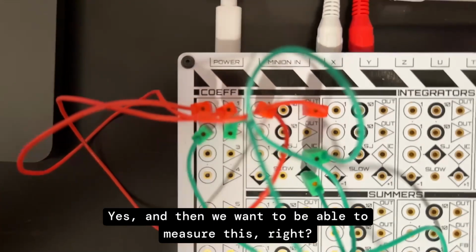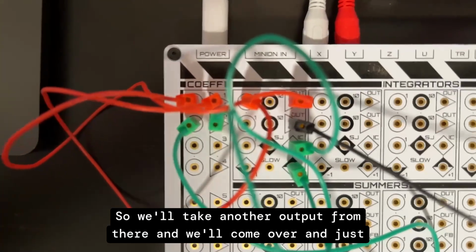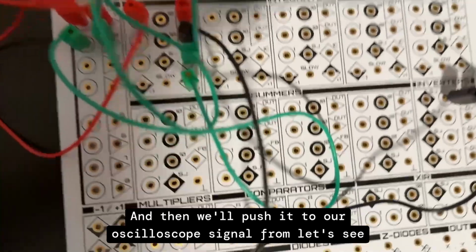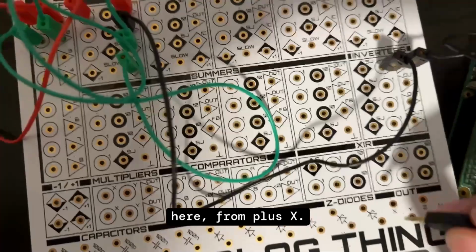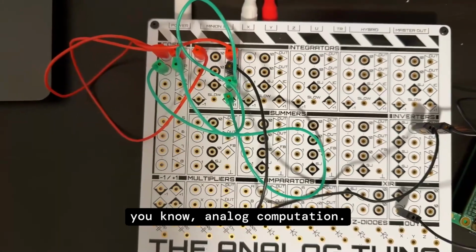And then we want to be able to measure this, right? So remember that this is going to be a minus x on this side, so we're going to need to invert it. So we'll take another output from there and we'll come over and just invert it here. And then we'll push it to our oscilloscope signal from, let's see here, from +x. Okay. All right, great. So there you go. This is kind of your bare minimum analog computation.